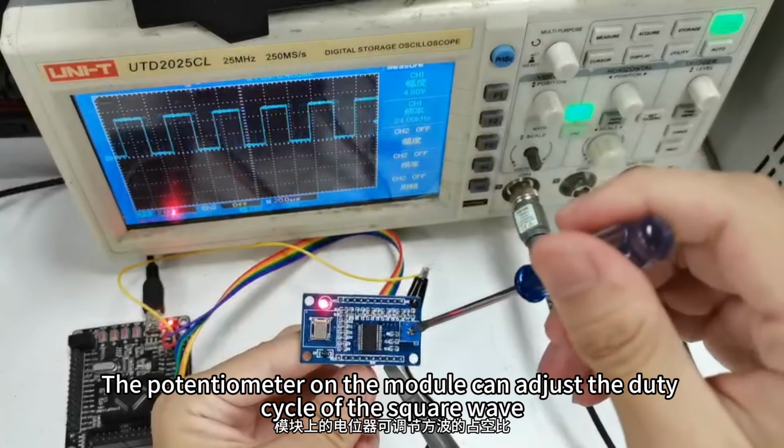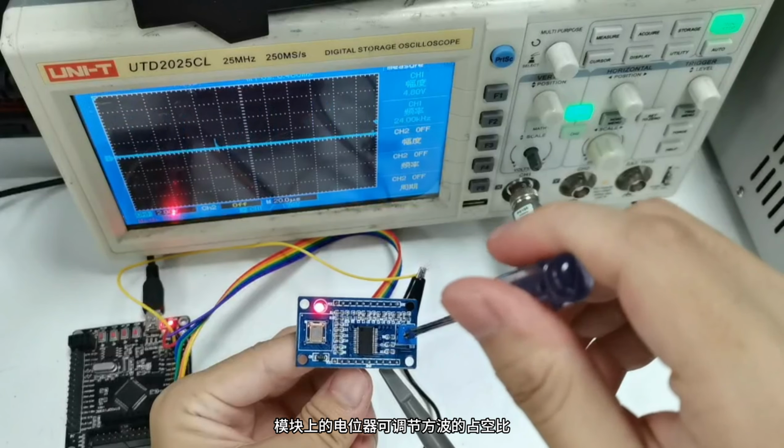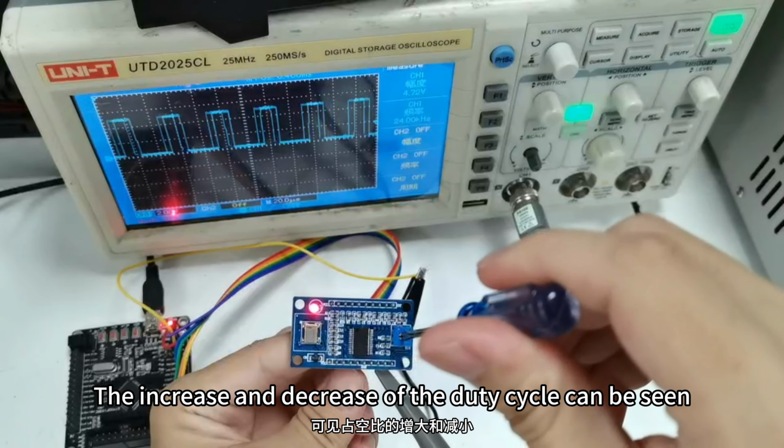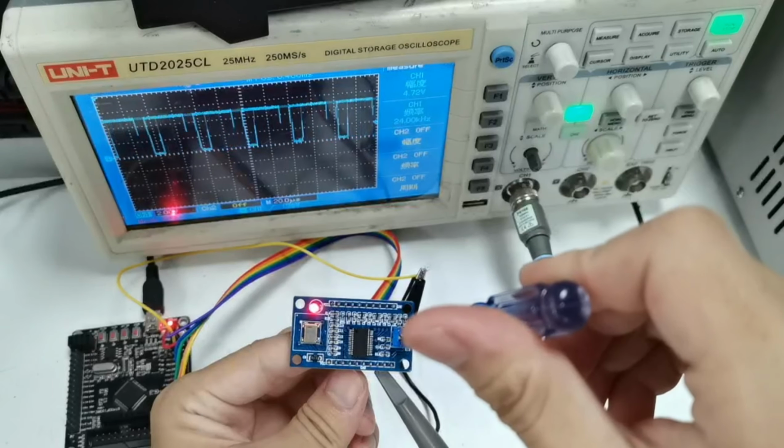The potentiometer on the module can adjust the duty cycle of the square wave. Rotate the potentiometer and observe the waveform again. The increase and decrease of the duty cycle can be seen.